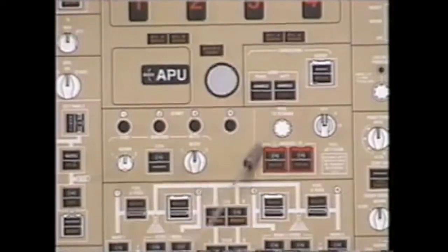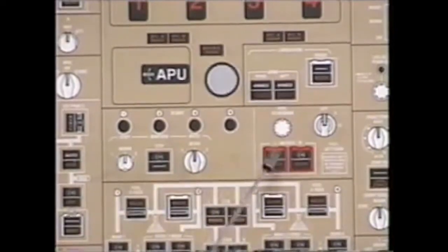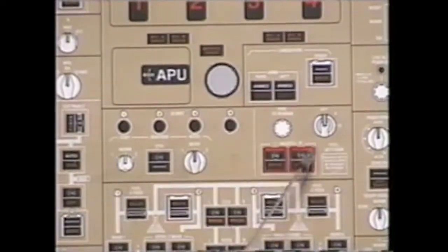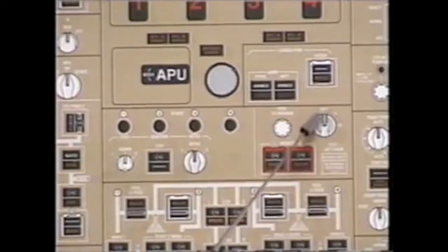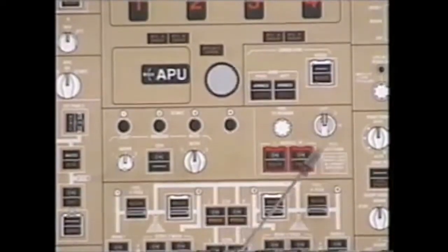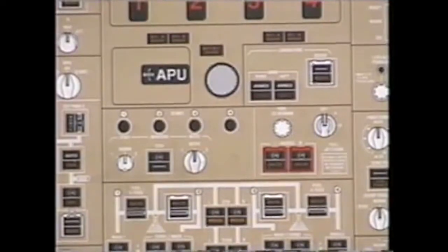To the right is our fuel jettison control panel. We have the jettison nozzle valves left and right, the jettison controller, and the fuel to remain. The important thing to remember here is even if you're on the ground with the jettison selector in the off position, you can physically open the left and or right jettison nozzles. Not something you really want to do. Please keep in mind if maintenance is fueling your airplane, you would be defueling the airplane. The only time we should use these switches is in accordance with the fuel jettison procedure.